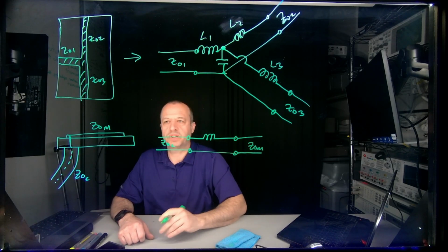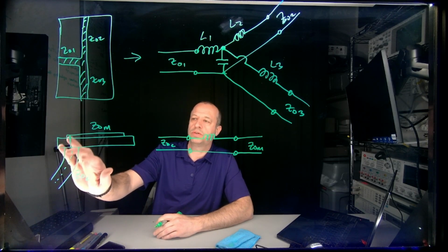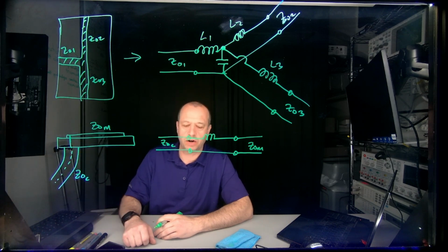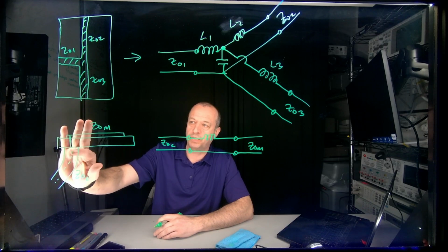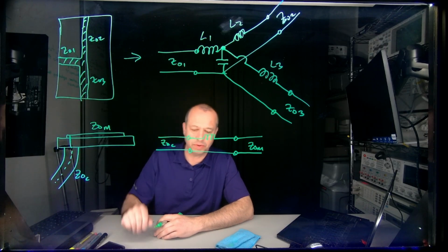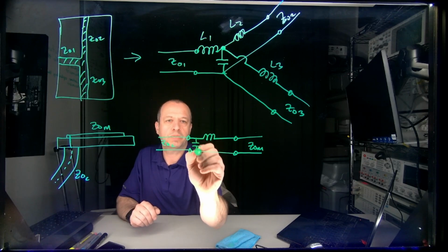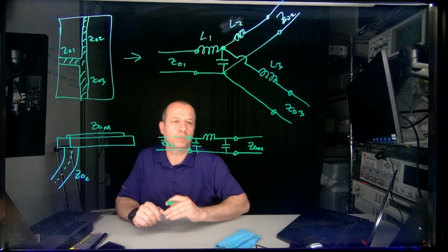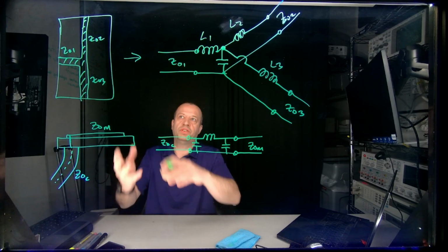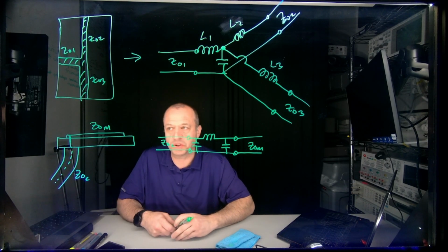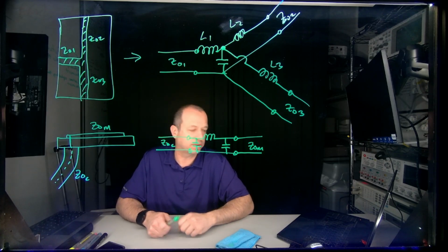And this is going to connect. But there's more to it than this, mainly because we have this cylindrical grounding shell here, and then we have all the capacitances between this and your ground plane if you have a ground plane like that. And so we need to attach our capacitances between those two. Okay, so that fills in the rest of the options. There are more than this, obviously. These are just the main ones that we're working with right now.